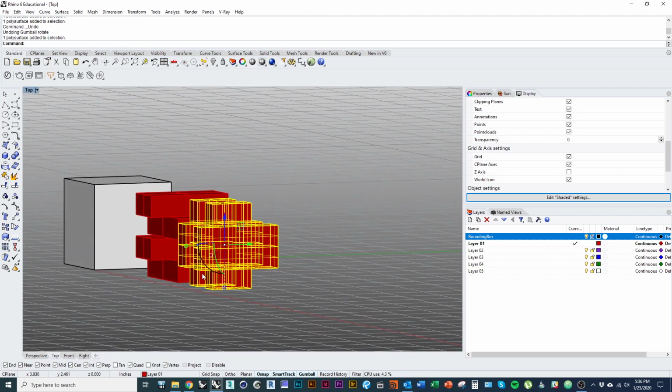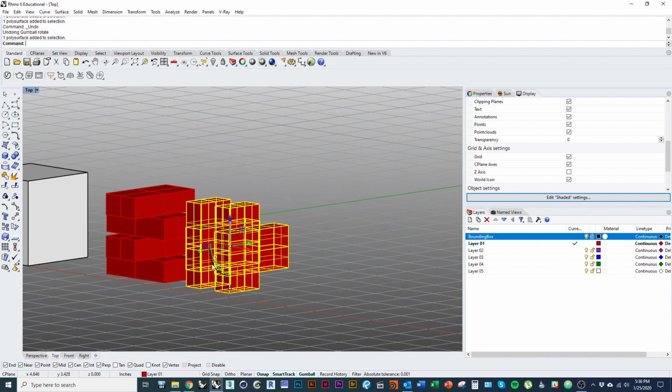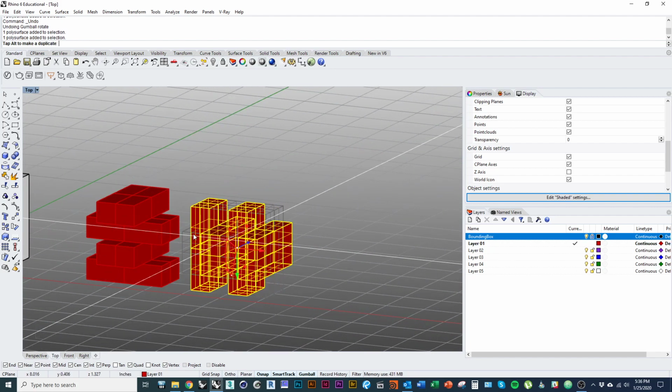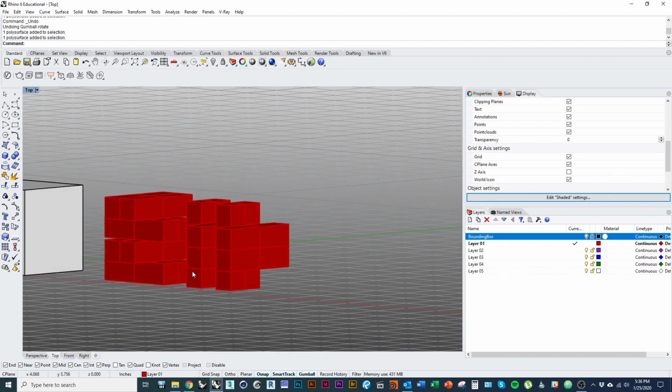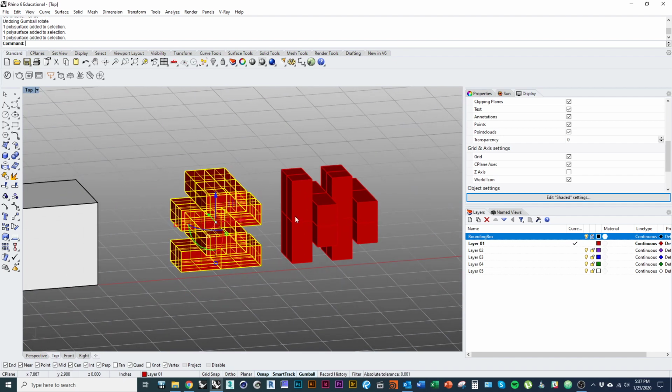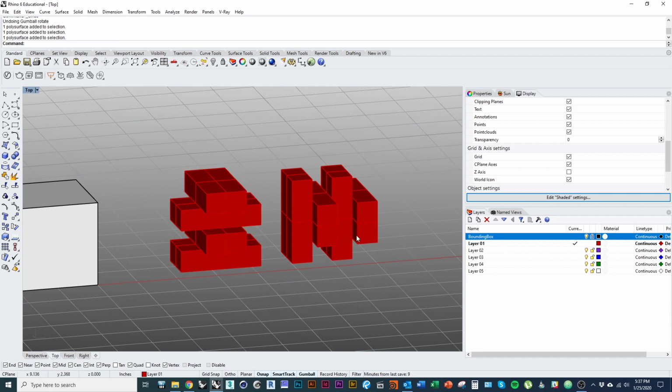But no matter what orientation I put it in, I'm going to have some kind of overhang, which means that I'm going to need some support in order to 3D print it. So that's just another thing to consider. With each one of your iterations, try and put it in a few different orientations, and just see how printable it is, and it may be worthwhile making a geometry that's a bit simpler to print in order to save time.